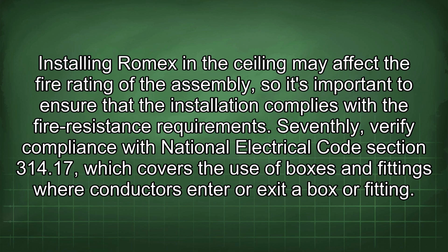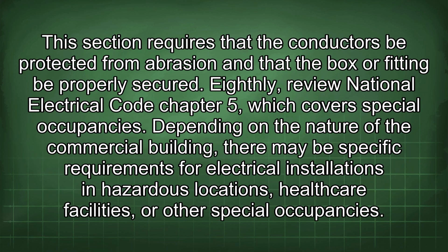Seventhly, verify compliance with National Electrical Code Section 314.17, which covers the use of boxes and fittings where conductors enter or exit a box or fitting. This section requires that the conductors be protected from abrasion and that the box or fitting be properly secured. Eighthly, review National Electrical Code Chapter 5, which covers special occupancies.